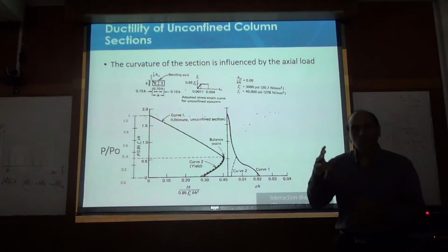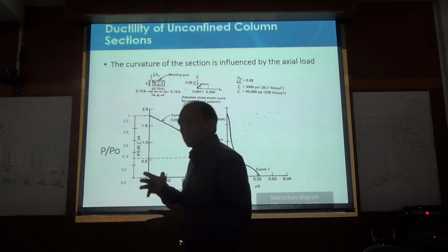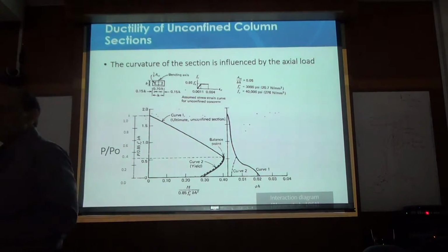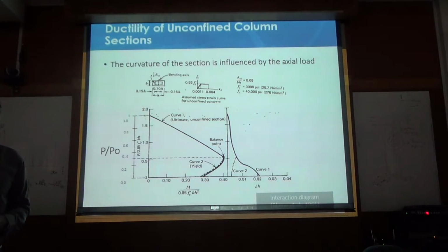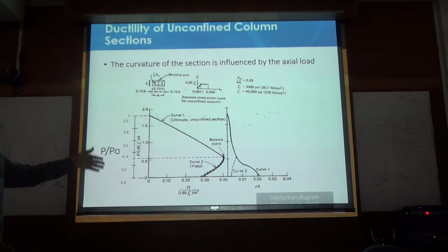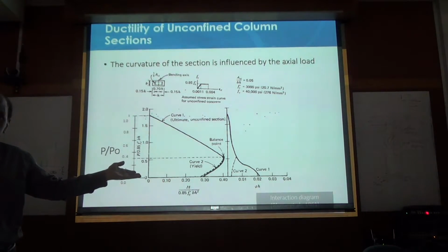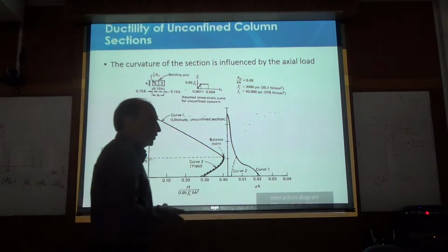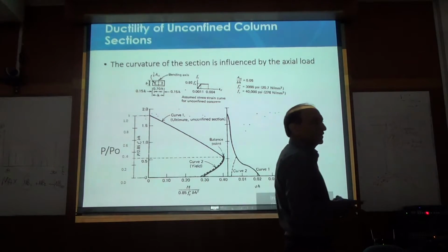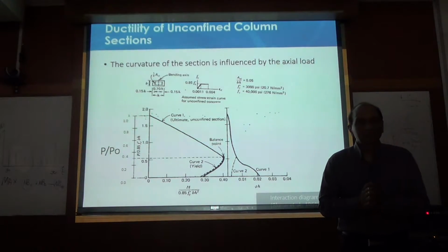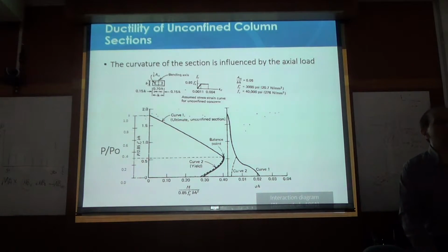So basically you move the ductility demand from columns to beams, which is easy to provide ductility. That is why we are studying both columns and beams. So if you cannot have high ductility in columns, design in such a way that beams take the ductility first. Clear? Okay. This is always the rule.